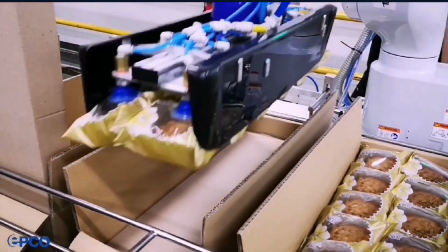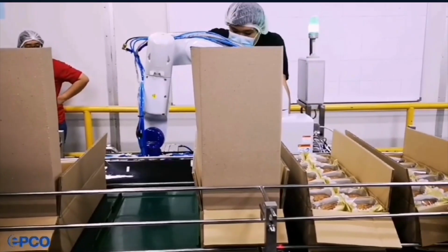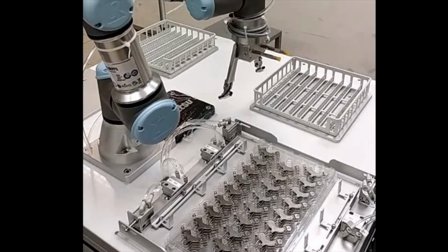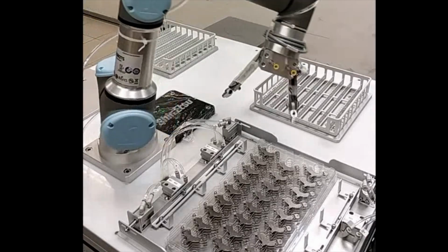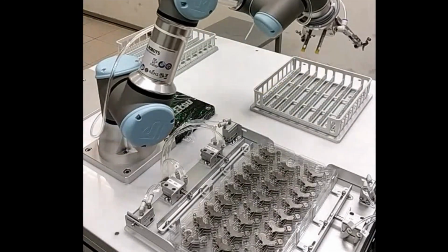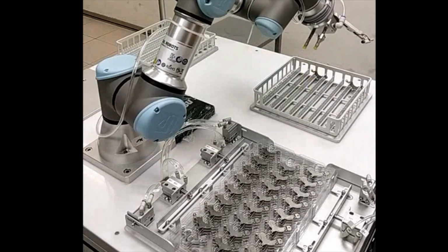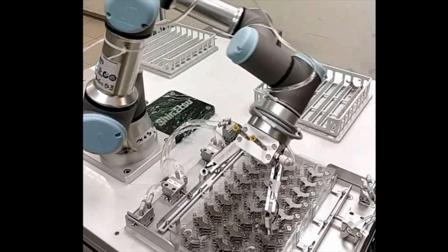Within this category, there are 2 subtypes. Select an industrial articulated robot when cycle speed is a priority. Select a Cobot, which is a collaborative robot, when cycle speed is not the main concern, when the process involves many different steps within one cycle, or when space constraints prevent you from installing safety fencing or guards.